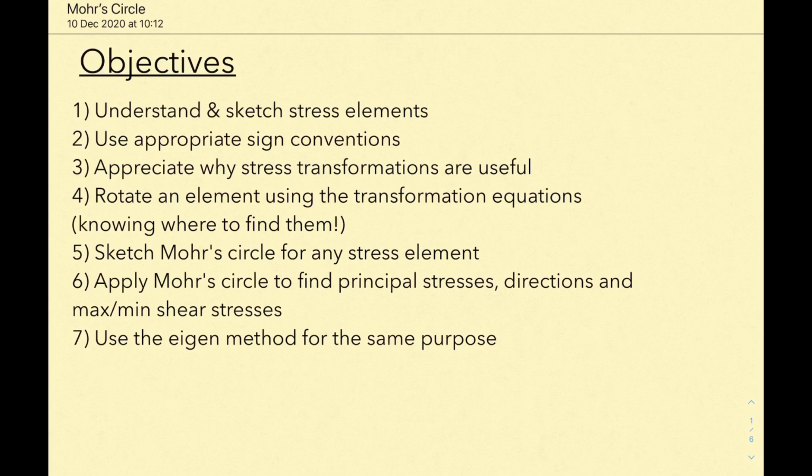Today we're going to cover Mohr's circle, and some of the topics we'll be looking at are understanding and sketching stress elements, using the appropriate sign conventions, appreciating why stress transformations are useful in the first instance, rotating the element using transformation equations, and building up to being able to sketch a Mohr's circle for a given stress element, using the Mohr's circle to find things such as the principal stresses, the directions, and minimum and maximum shear stresses, and finally also touching on the use of the eigenvalue method for the same purpose.